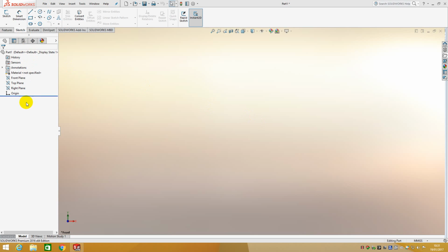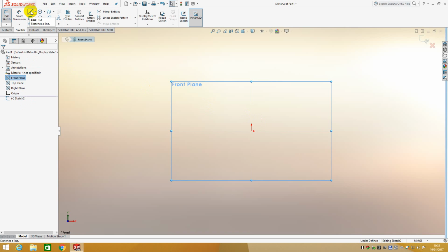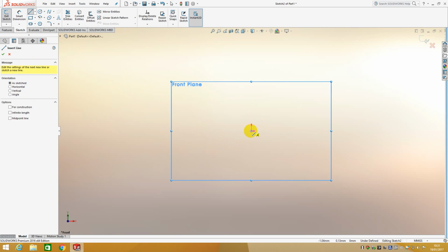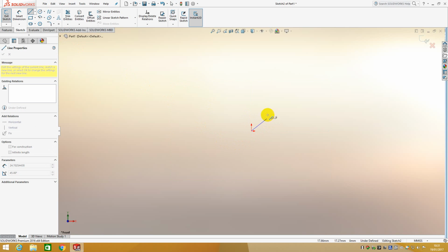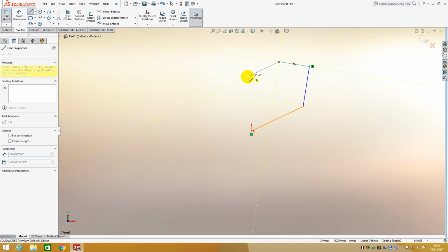So this is the line tool. If we select a plane, click on Sketch, select the line tool, and then as I click it drops an initial point. As you can see, as I'm dragging around the mouse cursor it's tracing a line between that first point and where I'm going to drop the second one. So if I just click again, it drops the second point, and as I keep clicking around the screen it keeps drawing a line to the next point in this chain.